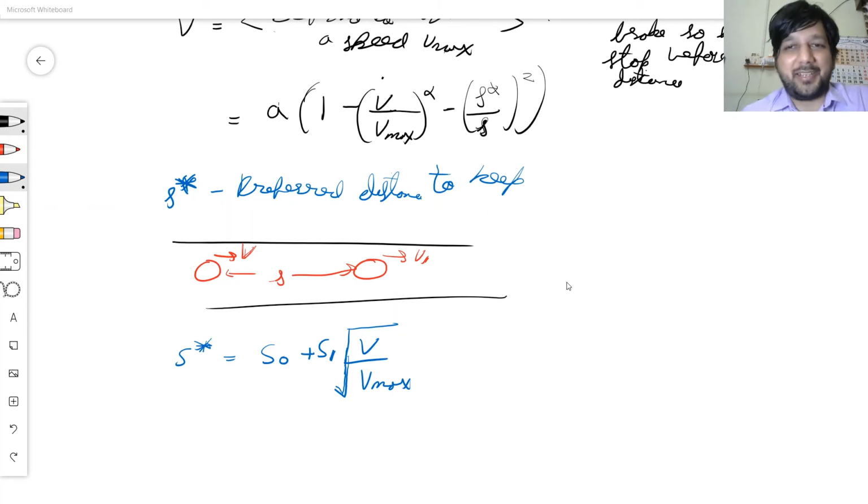The fundamental diagrams were made by observing real life data, so I'll regress it for all the powers. Currently, let me just take it intuitively that square root appears to be doing okay, that even when the speeds increase from 20 km per hour to 120 km per hour, the distance that I keep does not increase 6 times, so I kept a square root for it, indirectly saying that the larger the speed, the larger the distance, and that makes all intuitive sense.